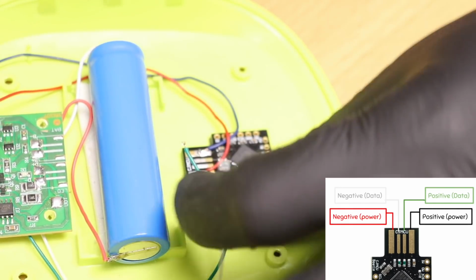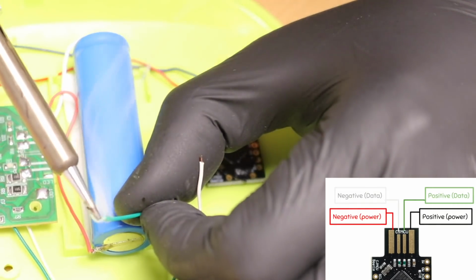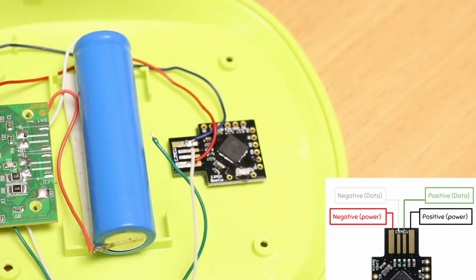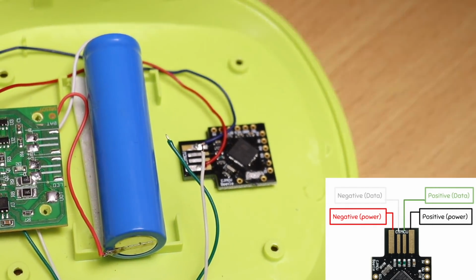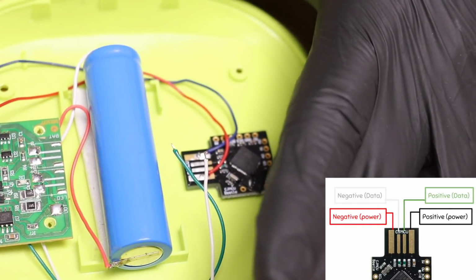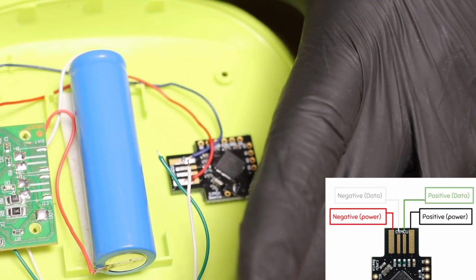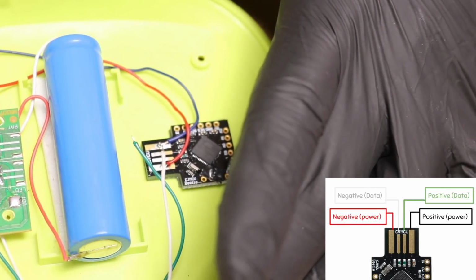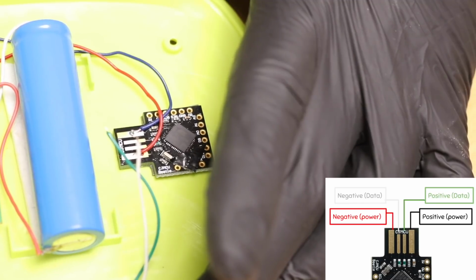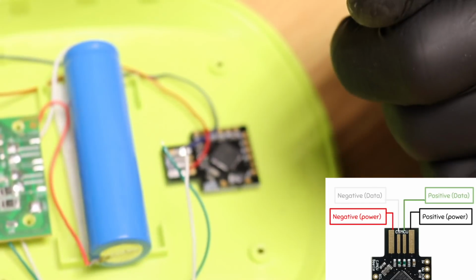And the data lines, these are the cables that you had to add yourself, obviously. Yeah, so generally USB devices like this, like lamps, will only come with two wires built into the main wire, the power and the ground. Now the wire we've added to this unit has all four. It has the two data lines and the power and the ground. Perfect.